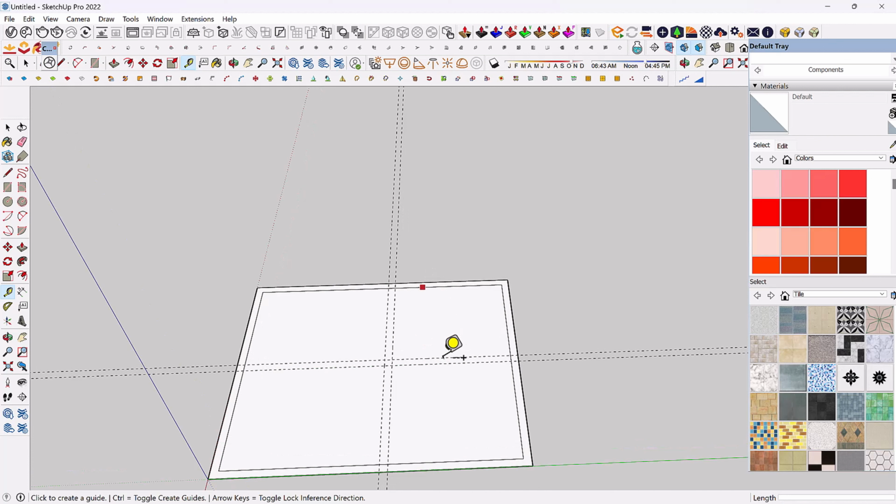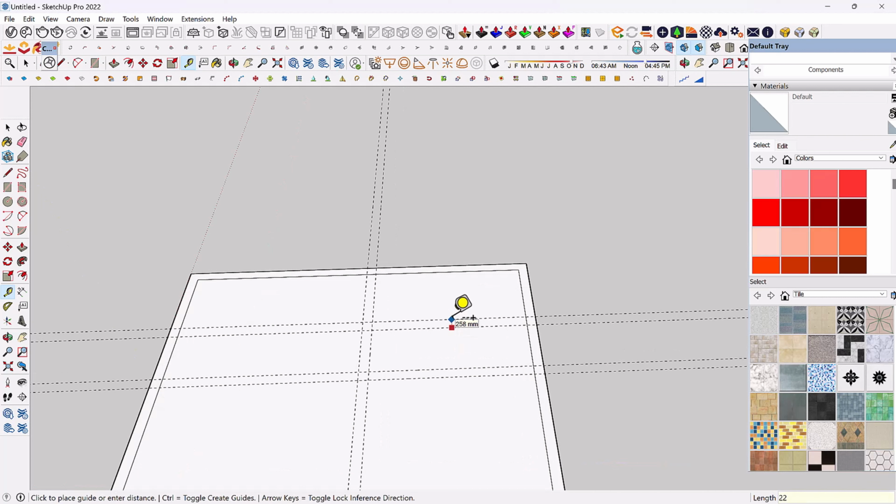Then for the toilet, the width is 1,200. Then I'm going to measure 1,200, enter. Then 225, and enter. So I'll check the remaining space. We have about 1,650 mm. In our formal drawing, on our sketch, it is 1,350. Okay, we can check it.